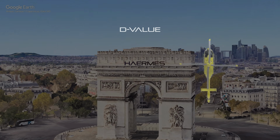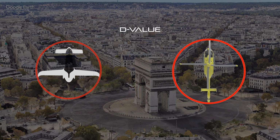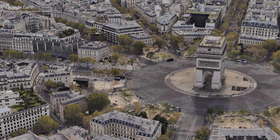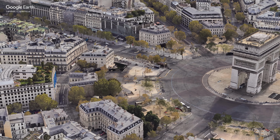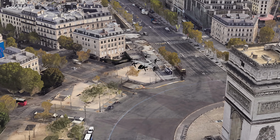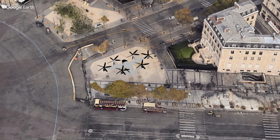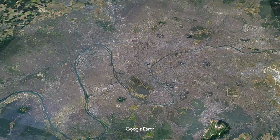While these regulations are in line with those for helicopters, they aren't always optimal for VTOL aircraft, because these aircraft tend to have irregular shapes, unlike helicopters, which all have the same dominant component for their D value due to their rotors. In addition to the platform size, regulations also govern the space above and around the vertiport to ensure safe vertical takeoffs and landings. This obstacle-free volume helps to prevent buildings, trees, and other structures from interfering with aircraft movement. Every VTOL aircraft will have slightly different procedure volumes due to the varying takeoff and landing dynamics of each model.